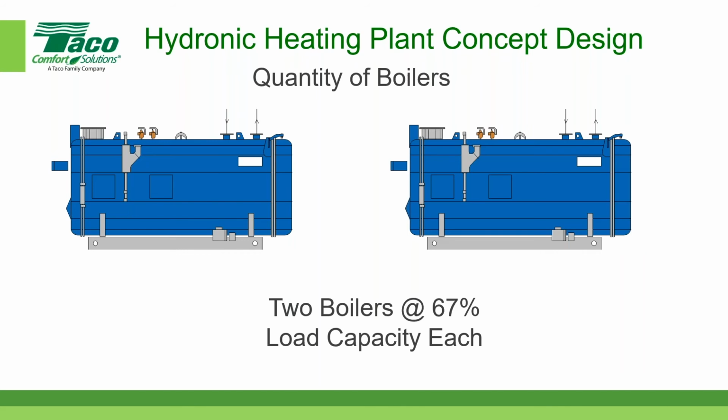So let's talk about another option for two boilers. Another option is two boilers at 67% or 2/3 capacity. One of the advantages of going from two boilers at 50% versus two boilers at 67% is that 2/3 capacity, when you look at the load profile of a building, especially during occupied hours, for a simple office building will probably handle more than 95% of the operating hours during the daylight hours. So for all practical purposes, if you should lose one of the boilers at 2/3 capacity, you probably have nearly 100% capacity for more than 95% of the daylight hours.